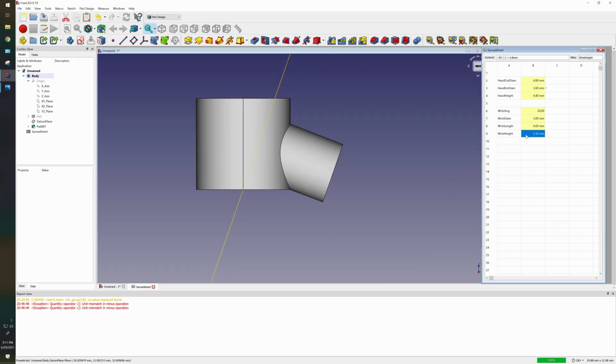Remember what I said of formulas? Whenever I have a formula, I'll put an X, a star here, just to remind me that's driven by another dimension, so that if I ever delete something and all of a sudden I see things breaking, I know where formulas could exist. Anyways, if you're fancy and you wanted to do the trig math to figure this out so that it comes out perfectly at the bottom, good on you. I'm more of a let's fudge the numbers till it works type of guy.